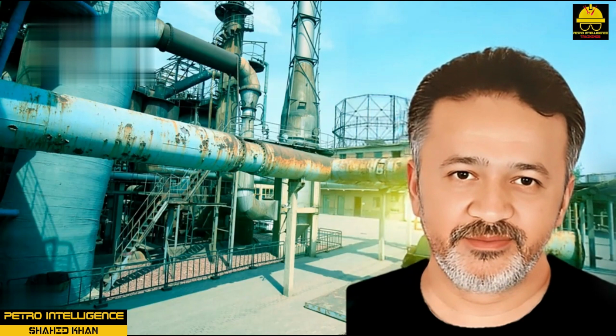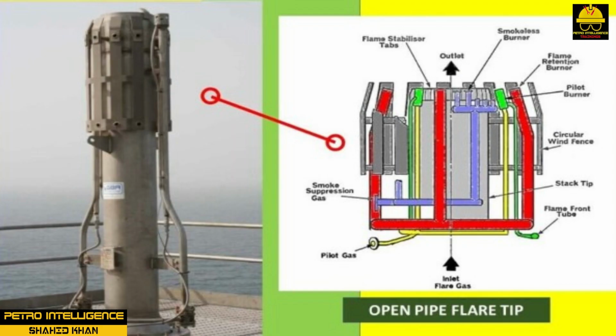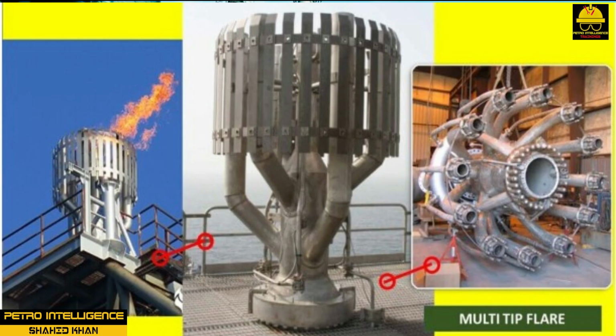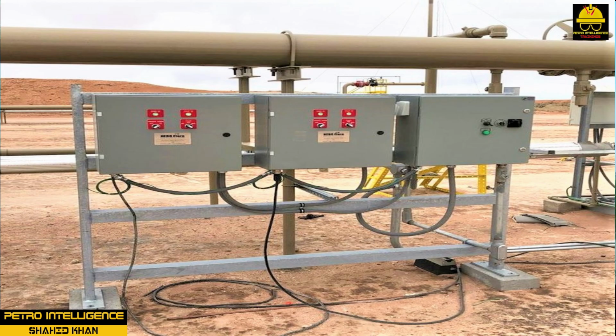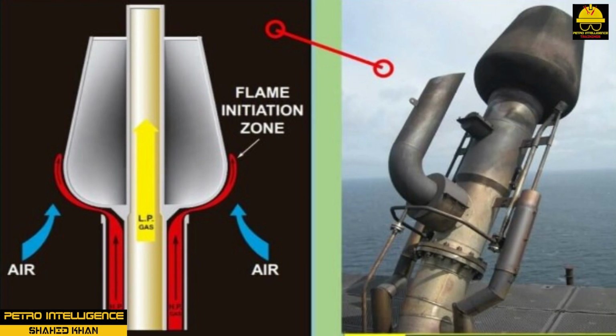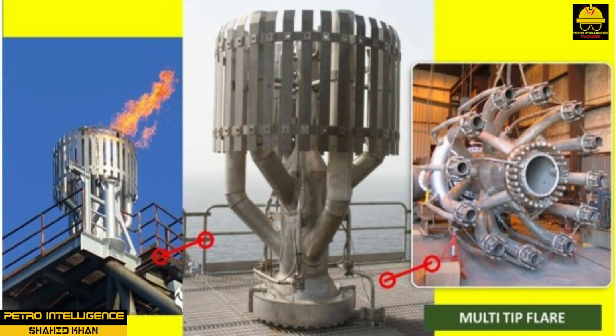Steam is piped to the burner tip of the unit flares to disperse and provide draft for burning off the gas without smoking and to protect the burner tips from the heat of the flame. Part of the steam flow to the tip is fixed and cannot be shut off. A manual loading station, which operates control valves in the steam line, remotely controls the remainder. These are adjusted as necessary to eliminate smoke at the flare tip.